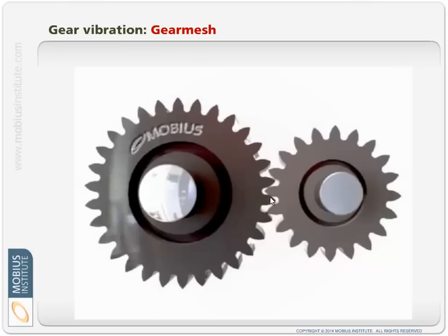In other presentations we talk about lubrication issues, but there's less than a micron between these two teeth, so the lubrication is incredibly important with gears. But from a vibration point of view, I haven't actually counted these teeth recently, but let's say we had 31 teeth or something like that, then 31 times the speed of this rotation, we expect some variation in vibration.